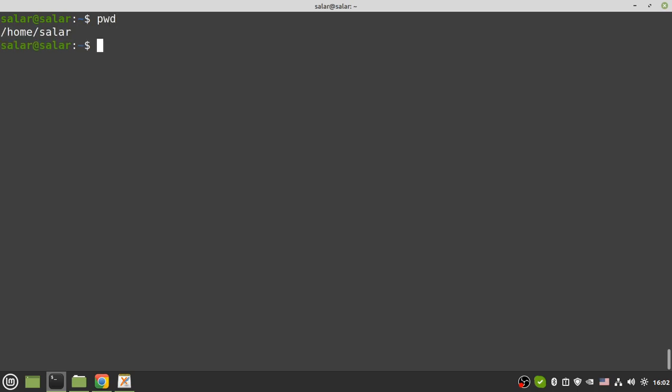Now I'm in the home directory, but if I press arm and press tab, it does not complete the name. Or if I write the whole name of my compiler, for example, arm-none-eabi-gcc, I get arm-none-eabi command not found. It can't find my command. Why? Because the directory of this command is not in the path.